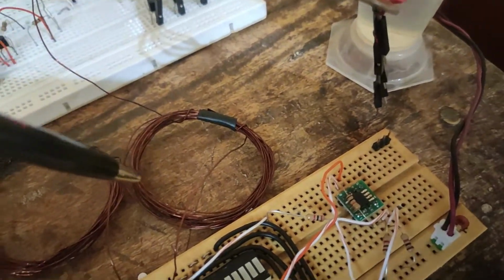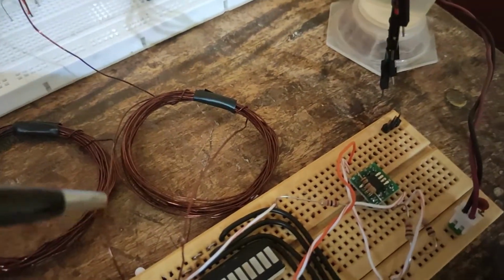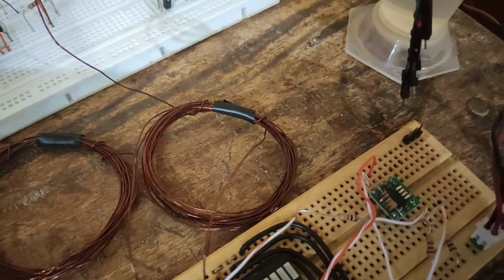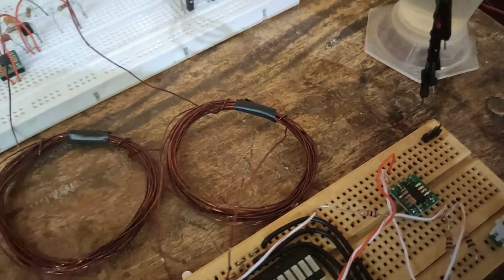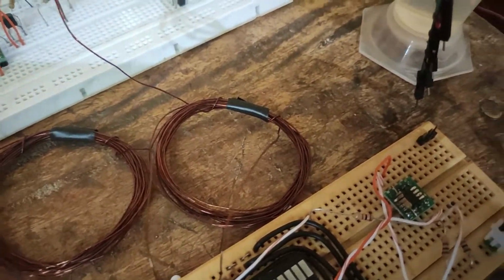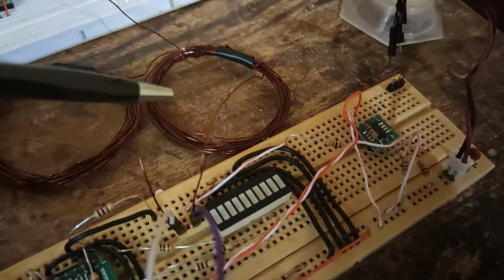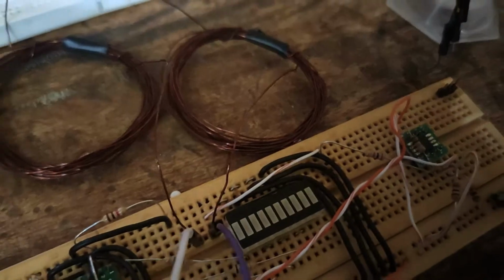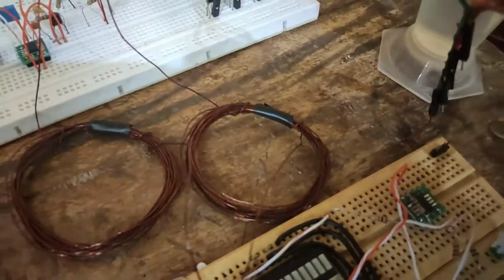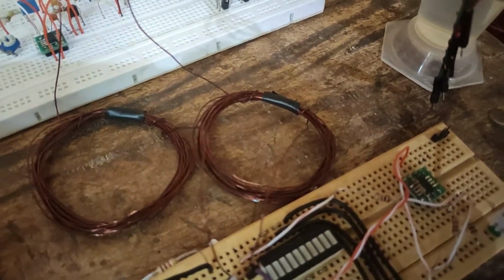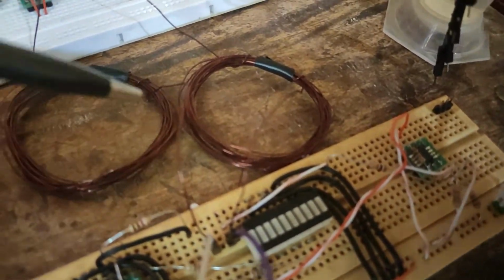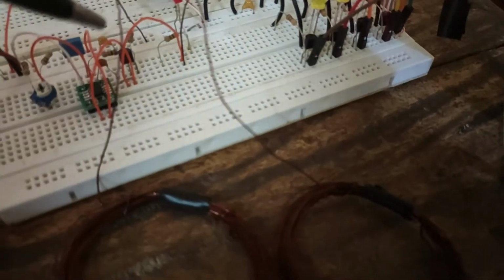I have taken some 3 meters just for demonstration. As we know, the current won't drop along the wire. We can consider it to be of any length, maybe up to 3 miles probably. So this current would be in the range of 0 to 20 milliampere, as the name of the circuit states. After that it loops back and goes to the ground.